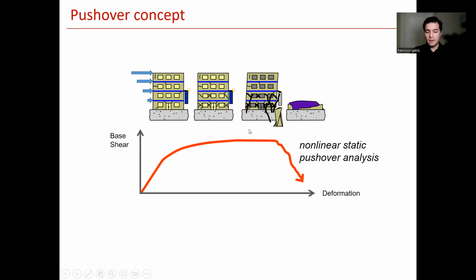In the realm of performance-based earthquake engineering, this figure has also been used a lot to show the different performance levels of the building, right? You can have a building that has minimal damage here, continues very functional, a building that has moderate damage, relatively functional, and then a building that has severe damage but hasn't collapsed, so it complies with the life safety target of the building codes, where yes, you have a lot of damage, but you have time to evacuate, and then an unacceptable response, which would be basically total collapse with high risk of losing lives.